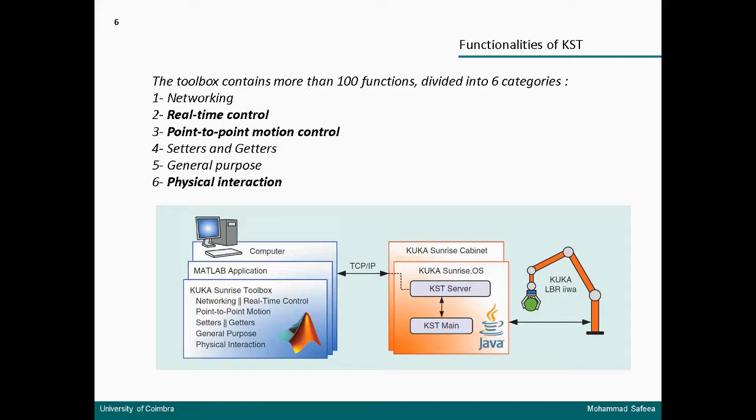There are general purpose functions that are used to calculate forward kinematics, inverse kinematics, the dynamics of the robot, and the various matrices of the manipulator, including mass matrix, the Jacobian, Coriolis matrix, centrifugal matrix, null space projection matrix, and other quantities.